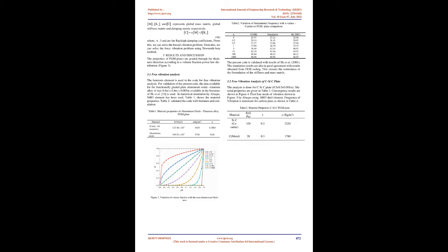Using the Green Lagrange strain displacement expression (11), the linear strain displacement matrix B has been worked out. The different participating element level matrices, such as the elastic stiffness matrix and consistent mass matrix, have been derived using the corresponding energy expressions. The element elastic stiffness matrix and element mass matrix are derived using the following relations.